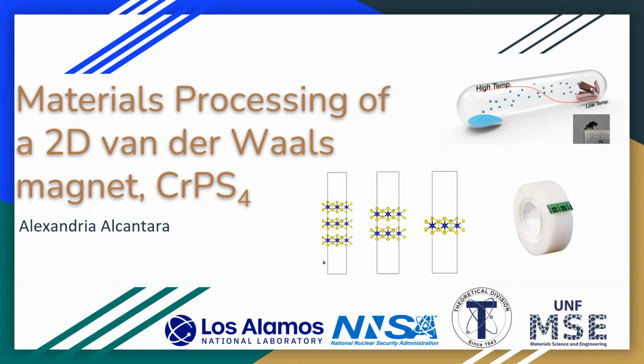So 2D semiconductors can be grown through chemical vapor deposition. However, because chromium thiophosphate is a ternary compound, it must be grown through chemical vapor transport. After bulk crystals are grown, they can be extracted with scotch tape, and then the amount of layers can be identified through Raman spectroscopy. So we're going to look at these procedures in a little more detail with the presentation I have here.